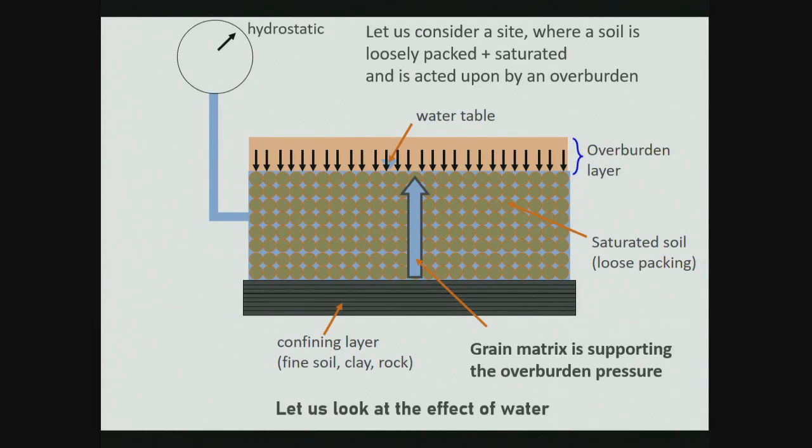In the second case, imagine that you have these grains, but in addition to that, you have some very small grains as well. So those grains will naturally occupy these void spaces. So when they are occupying these void spaces, in the event of an earthquake, you have relatively less chance for these soil grains to roll and slide past each other. And once you have restricted the ability of these grains to move, you have actually restricted the pore water pressure to increase to the same levels as before. So with increasing fines content, you will have less chances of liquefaction.